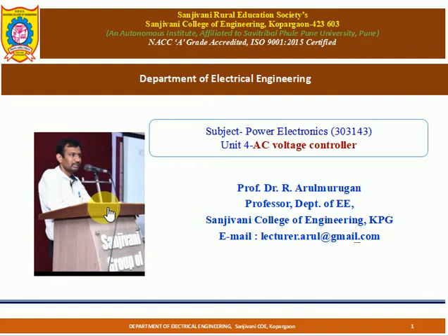Very frequently you want to do maintenance. There is an adjusting knob, and at the bottom of the knob there is a contact point. Day by day the thickness of that point is reduced, so frequently you want to replace that point. Another thing is that whenever you vary it, a small spark can occur. So cost wise the auto transformer is more. So there are limitations.